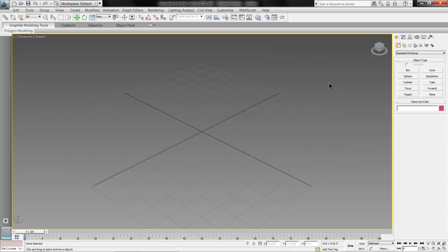Okay, so then we'll go to the command panel at the far right. Here the first 2 tabs at the very top are the ones you want to always look at. The very first tab is the Create tab, and immediately below that you have your subcategories. Geometry is selected by default, that's your 3D objects. Next is Shapes, those are 2D objects.